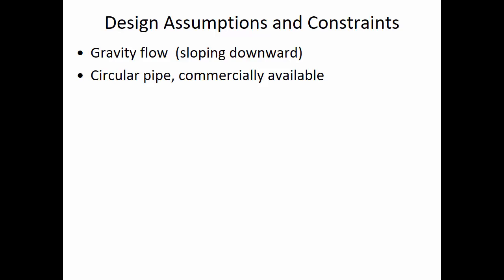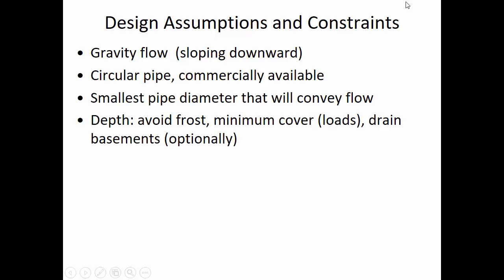Here in Huntington, where they do have old vitrified clay pipes that may be cracking, what they sometimes can do is put a liner in those pipes, where it's not like they have to go down there and press the liner in, but there's a way of taking it inside out and kind of blowing a liner into place using water or compressed air, kind of like inflating one of those really long balloons that a balloon guy would use to make a dog or whatever. So they have those balloons and they can put it on the inside of a cracked pipe and then it becomes watertight. So there are some ways to refurbish the old pipes. Sometimes they have to be completely removed.